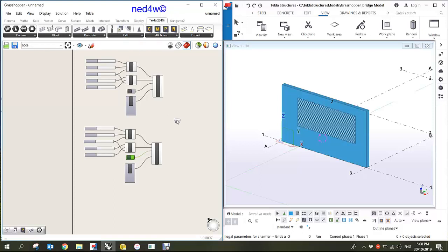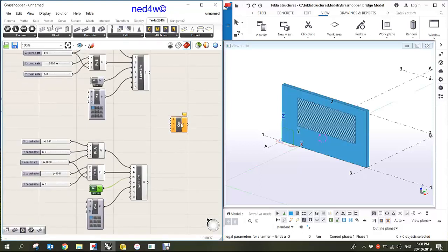So click on the part cut, add this one. As you notice here, I have this P as the part to be cut, C as the cutting part, and then D is to delete the cutting part. So I'm going to link this beam 1, which is the wall, and then this beam 2, which is the opening, all right?